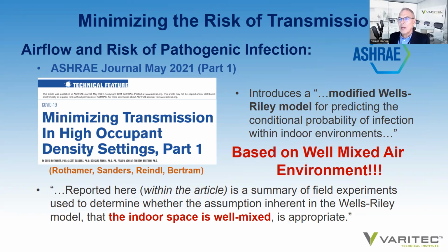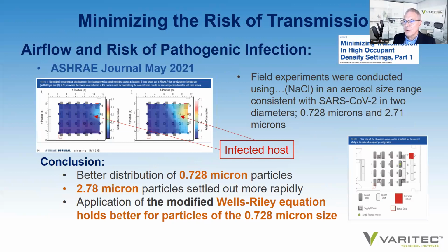So the ASHRAE Journal article, part 1, introduced a modified Wells-Riley equation applied to a CFD modeling program. The article evaluates and reviews a summary of field experiments used to determine whether the assumptions inherent in the Wells-Riley model in an indoor space are appropriate. But notice the qualifying term, well mixed. And this is a very important consideration.